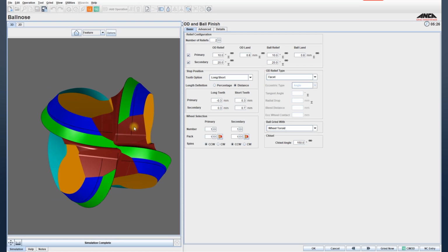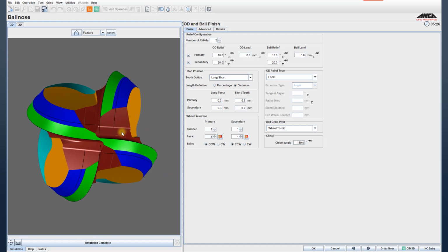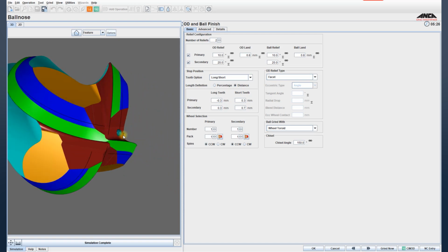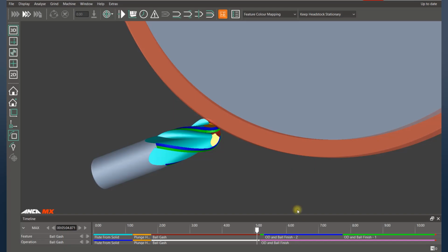These black lines actually indicate the grinding wheel effector point tracking behind the primary and secondary leaf. Now this is quite beneficial, especially when you want to see where the stop distances of your grinding wheel are. So let me just switch my software to Sim3D.